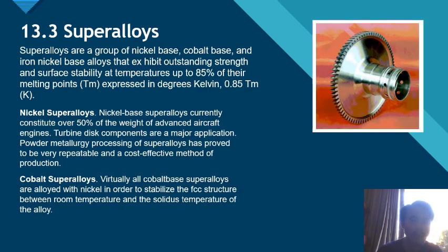Superalloys are a group of nickel-based, cobalt-based, and iron-nickel-based alloys that exhibit outstanding strength and surface stability at temperatures up to 85% of their melting points, Tm, expressed in degrees Kelvin, or 0.85 Tm Kelvin. Nickel-based superalloys currently constitute over 50% of the weight of advanced aircraft engines. Turbine components are a major application. Powder metallurgy processing of superalloys has proven to be a very repeatable and cost-effective method of production. As for cobalt superalloys, essentially all cobalt-based superalloys are alloyed with nickel in order to stabilize the FCC structure between room temperature and the solidus temperature of the alloys.